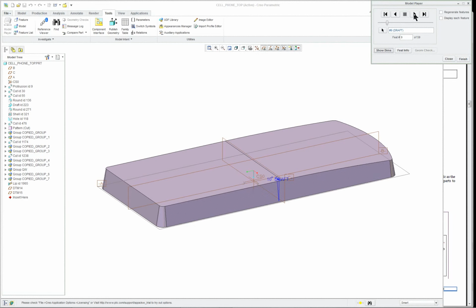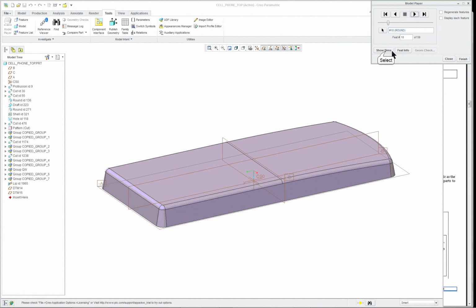And the draft was added. And now with the protrusions you can add an angle, and if it's a small enough angle you can put it in with the first command for your extrusion.